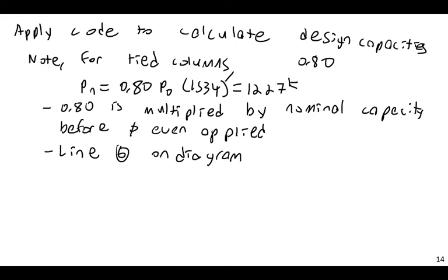So here, and then we have that. Okay, so then let's look at our phi factors. Basically, I'm going to go through each of these and calculate the appropriate phi factors. I have points 1, 2, 3, 4, 5, etc., and I'm just going to calculate them based upon that. So I have points 1 through 5. I'm going to calculate point 1a, point 2a. Basically, 1 would be the original point, and 1a would be the phi factor, the reduced point.